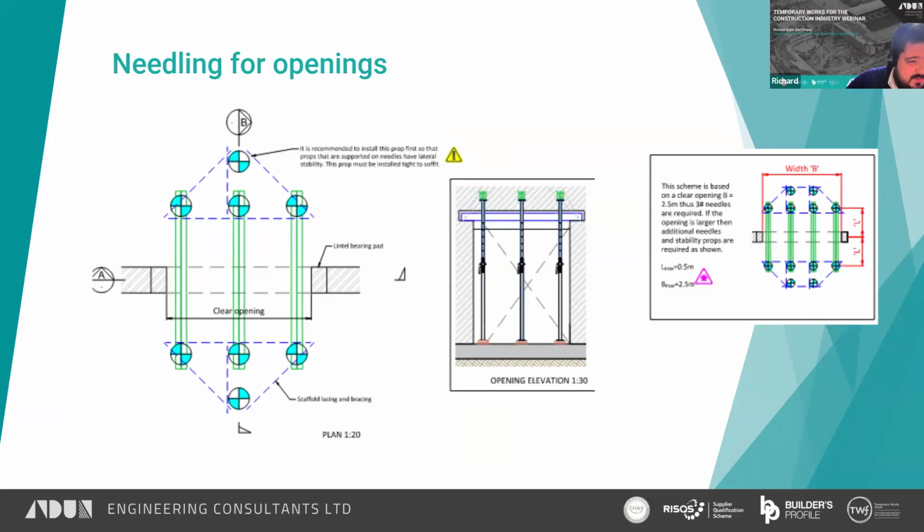And now I'm moving on to some needling. Now, the extent of the needling at Mould was everywhere. There was needling on every second wall and throughout the building, just because they were rearranging all the corridors and making new rooms everywhere. So what we had is, you might notice, these are very similar to the designs Josh was showing off earlier, where you just have the simple needles going through the wall and you leave enough space to install the lintels at the top, and then you can create your opening quite easily.